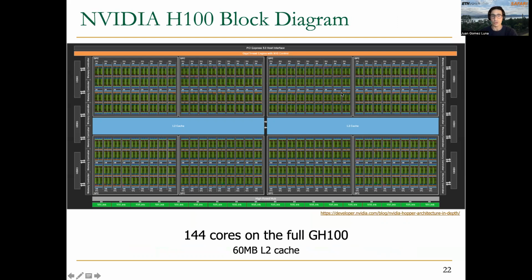Inside the GPU cores, there are different memory spaces like registers, L1, or the scratchpad memory that is called shared memory in NVIDIA terminology. These GPU cores, or streaming processors, or SMs, as they are called by NVIDIA, have access to the L2 cache, and then they also have access to the external, off-chip memory.